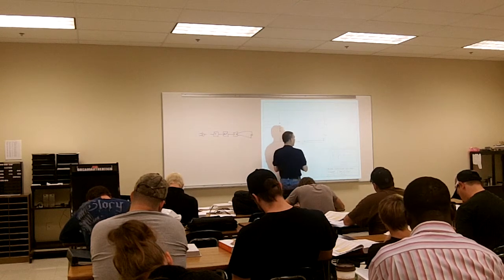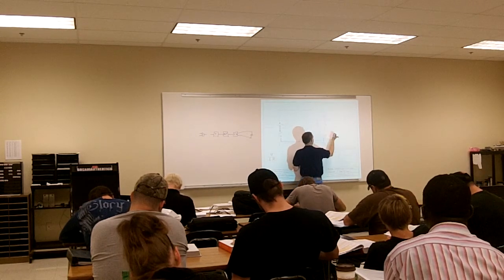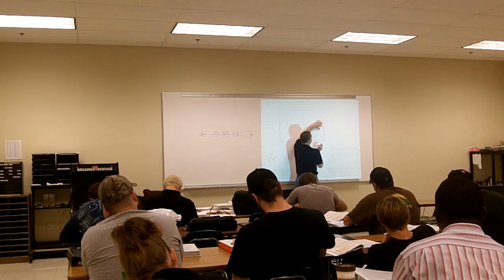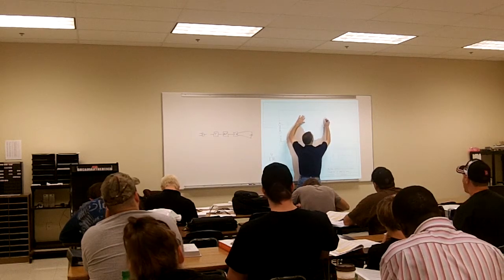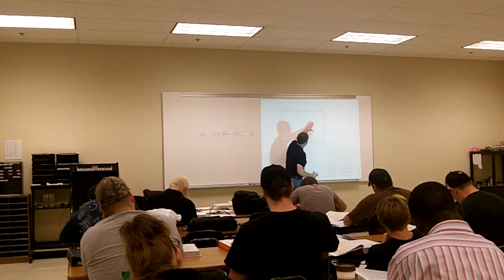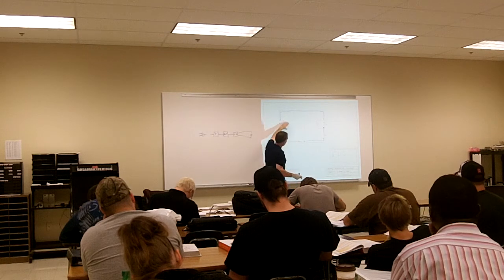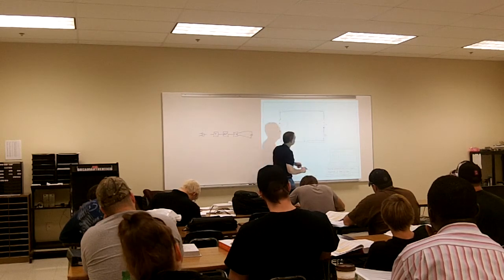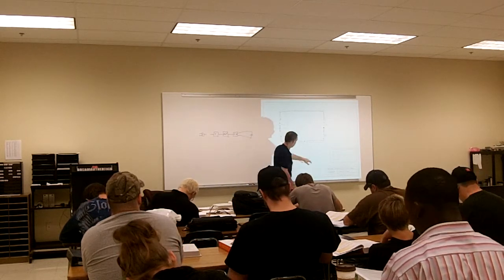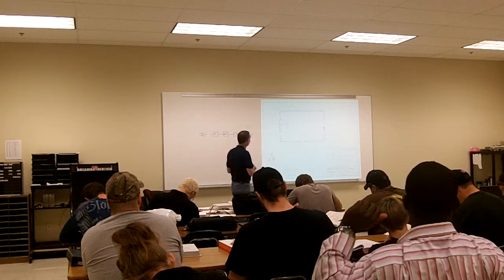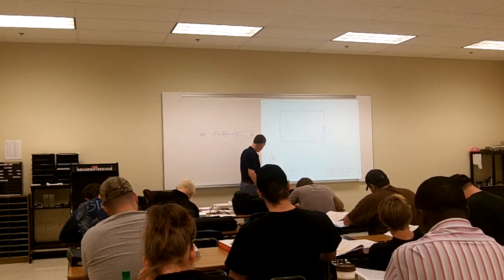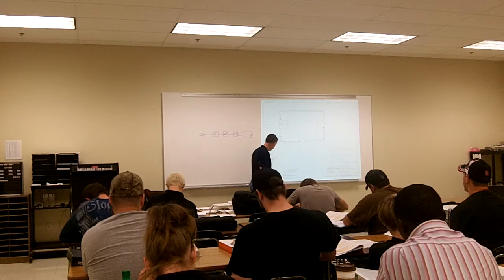Then up through my current meter. We especially like to make sure that we get our current paths going through our current meter because there is no such thing as negative current. It's going to go up through the resistor, and that's going to have polarity, so negative, positive across the resistor, and then back into my power supply. These are just showing you how to hook up your voltmeter. After chapter 3, I get rid of these voltmeters. Right now I'm just showing you where you hook up your voltmeters, your current meters, and your ohm meters. So that's our current path. You always want to draw that on all your schematics, and at the same time we indicated polarities on all components.